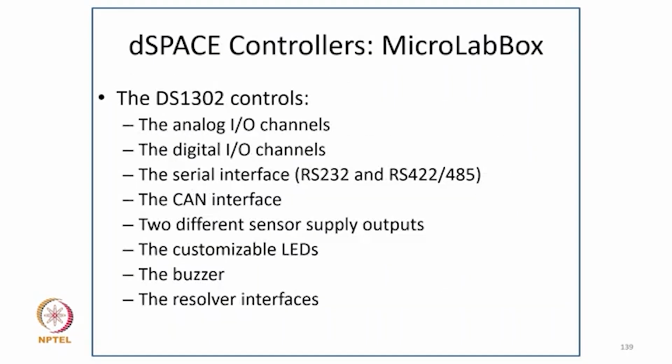So the DS1302 controls the analog input-output channels, the digital input-output channels, the serial interfaces RS232 and RS422/485, the CAN interface, two different sensor supply outputs, the customizable LEDs, the buzzer, and the resolver interface.